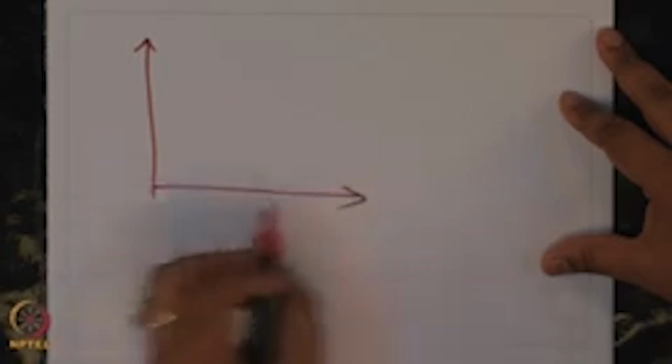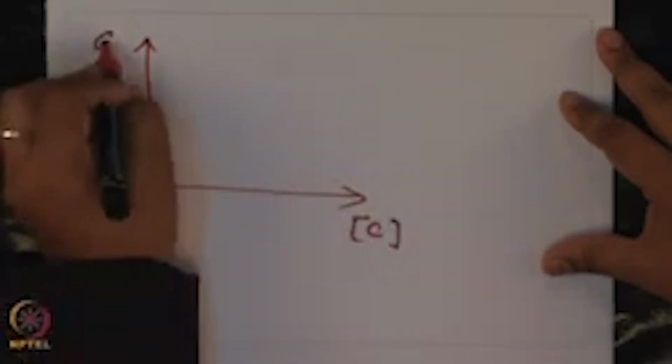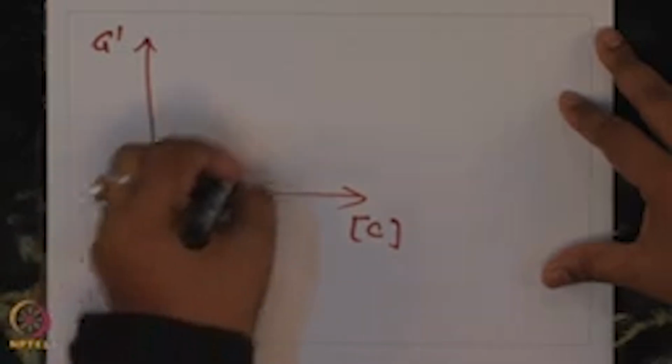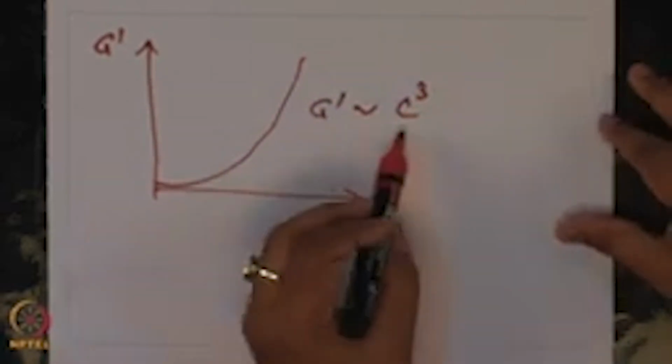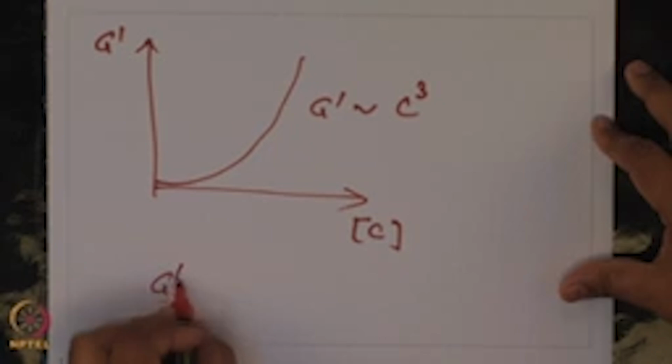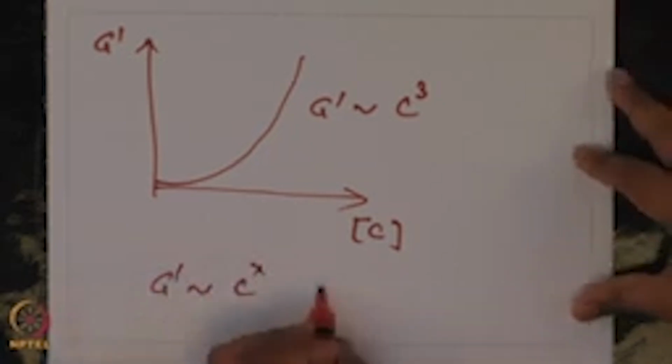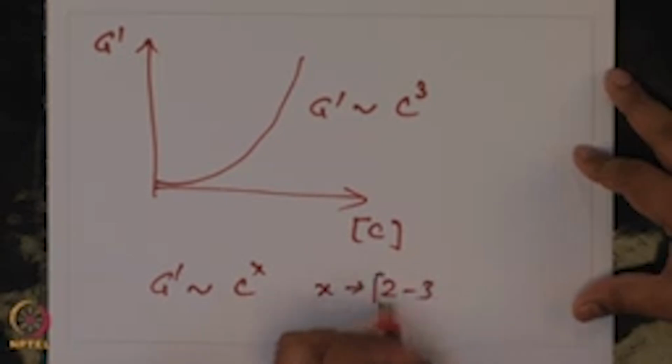Okay. So, over the last two lectures I had spent considerable amount of time in studying the behavior of collagen networks, right. So, what are some of the experimental observations that we observed? One was the dependence on concentration, right. If I have concentration and I am plotting G prime value, I will have values which will scale like this, where G prime roughly scales as concentration cubed. For other biopolymer networks, G prime will still scale as C to the power x, where x can have any value between 2 and 3.